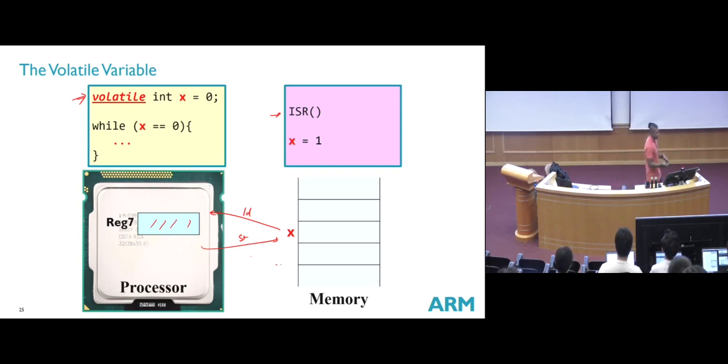Okay, so sometimes you will see that, I never use volatile, it still works. How come? Again, it depends on how the code is written, how the code is optimized. In some cases, you may say that I never use volatile and it still works, it happens to be the case, because of maybe the code structure and what you're doing with the variable. But it's always good practice to put the volatile keyword if there is a shared variable between the interrupt and the main code.